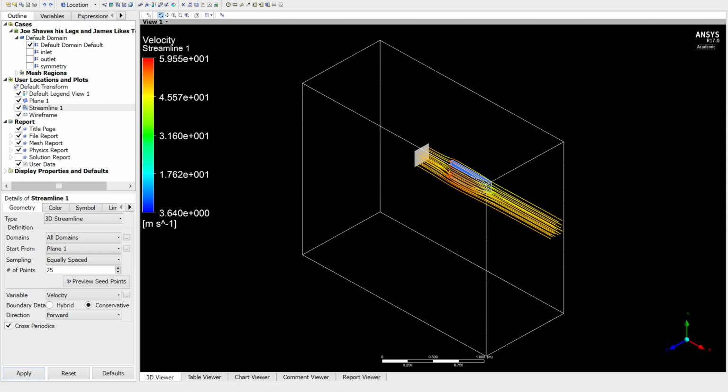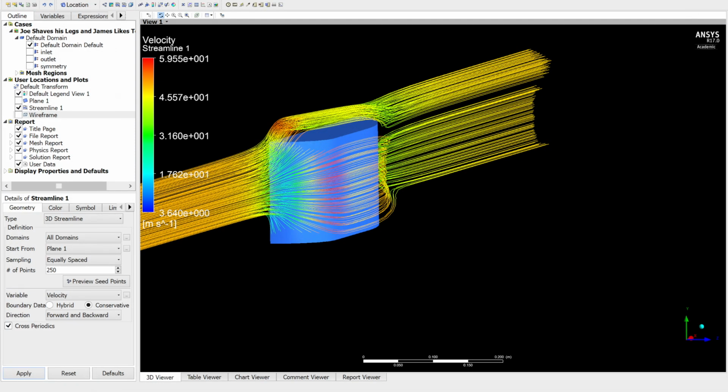You can use this to run CFD on pretty much any simple aerodynamic device, but you should be careful when running CFD on stuff like louvers and end plates, because there's a lot of more complicated meshing parameters that I didn't go into in this video. We'll go into them at a later time, but for now I just want you guys to start getting comfortable and playing with CFD. That way when we get into the more advanced stuff, you aren't overwhelmed or caught off guard.